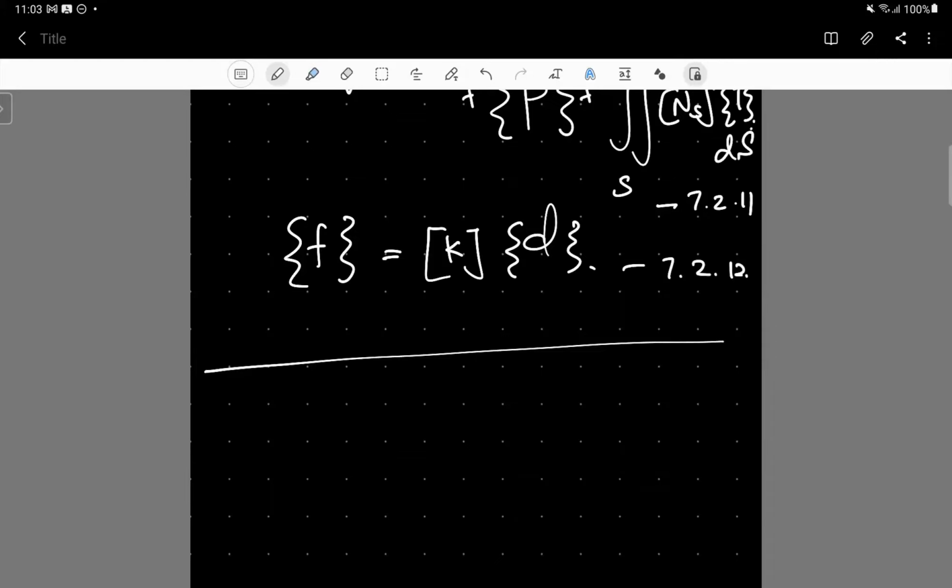Without simply clicking the buttons, you should know what is really happening within this problem. You will see that evaluating the integrals of such elements having a large number of degrees of freedom is not easy. For that, we will use special numerical techniques. We will quickly go through the Gaussian quadrature numerical integration scheme, and see how these numerical integration schemes are applied for solving such complex problems.